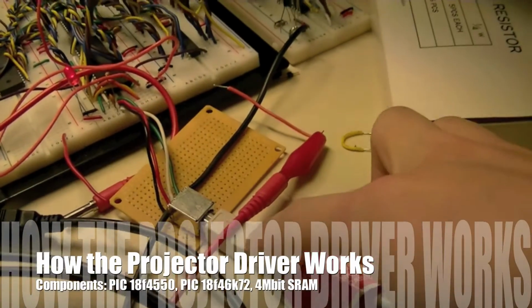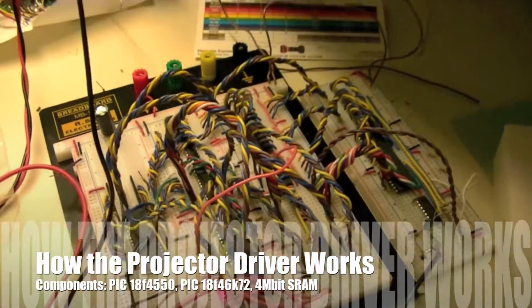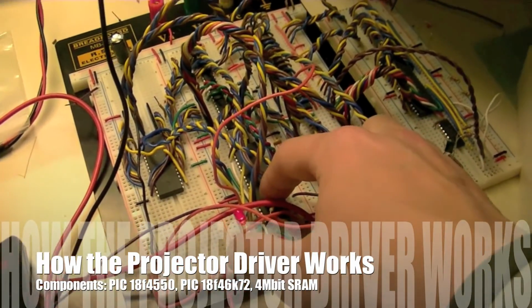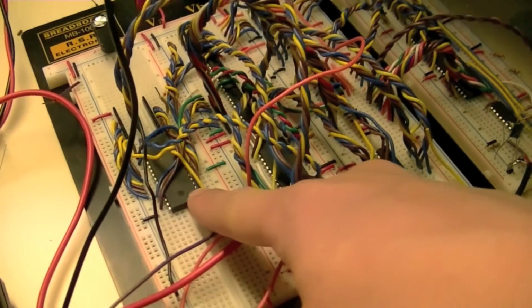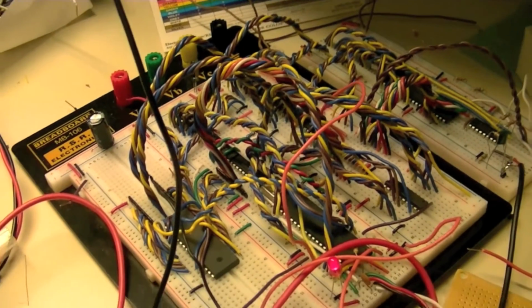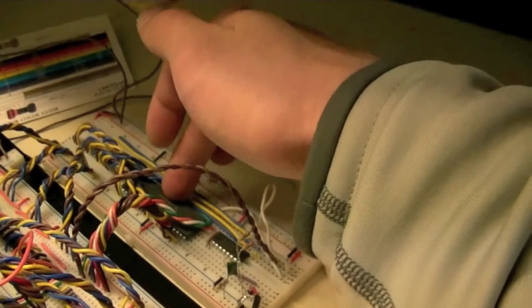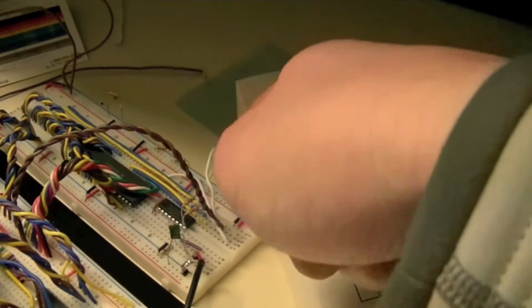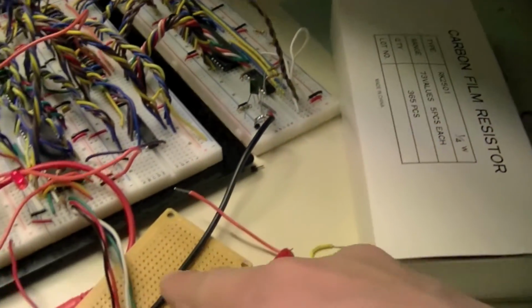The data from the computer goes through USB, comes over here to the image parser system. Right here, the image parser saves the image data to the SRAM, and it saves 3 images because that's how many angles we're projecting. That data is being read here by the projector driver, which translates the data to a composite video signal that goes to the projector way over here.